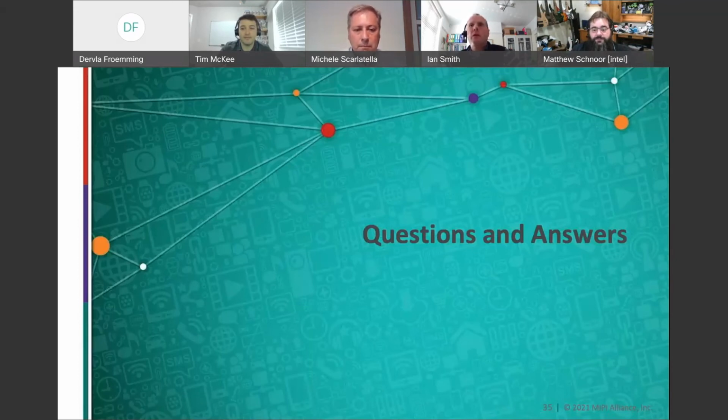Yeah, okay, thank you. So moving on, again, we've got lots of questions to get through. I want to clarify: does the I3C HCI replace the I3C master? So an I3C HCI does specify a master or bus controller inside of it that is actually in charge of the bus and sends the commands, gets the responses, monitors the IBIs on the bus, receives those things, and makes those available to the host in a way that is abstracted, that is, has a defined interface.